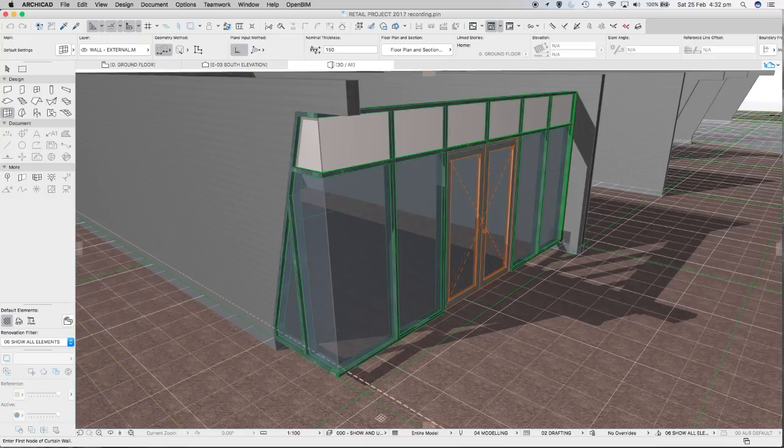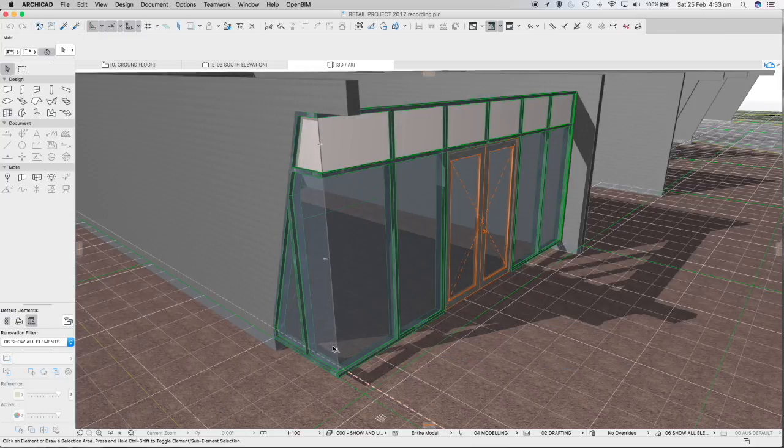So in plan view, you'll be able to draw that line across the front and then that line across there until you then press OK to finish the command. That'll then make this turn the corner nice and neat and tidily very easily. But what it won't do then is put this angled shape in the elevation view of this panel. It'll just be a straight wall with the height up there.